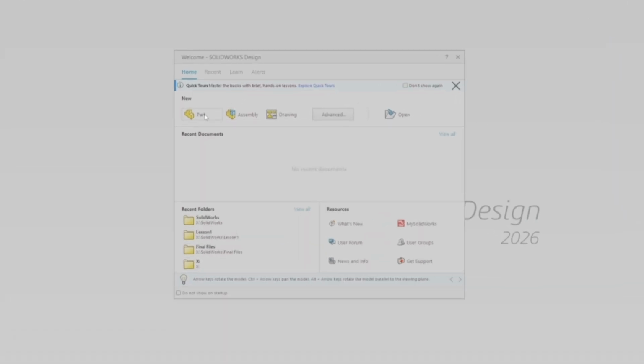So one thing to make sure we understand fully about CAD and CAD model architecture is that the part holds all of the information. So an assembly is going to be working off of a part. You can't work on an assembly until you have parts to put into an assembly. The same goes for the drawing. You cannot make a drawing until you have a part that can go into that drawing. The easiest way to think about it is that the part is the source of truth, or the source of all the data, while the assembly and drawing are downstream for that, or things that we'll address later on in the design process.